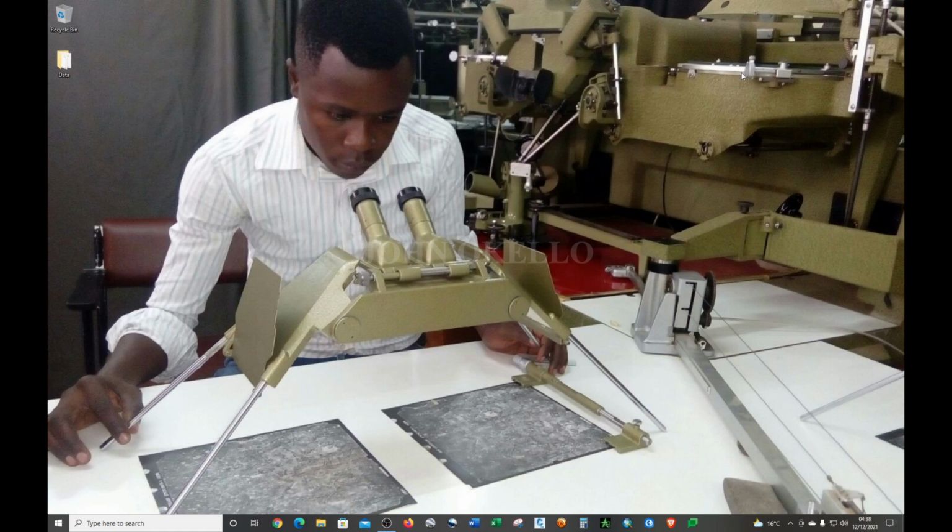By definition, digitizing is the process of converting geographic data, either from a hard copy or a scanned image, into vector data by tracing the features. During the digitizing process, features from the traced map or image are captured as coordinates in either point, line, or polygon format. And these points, lines, and polygons are what we call in GIS feature classes. By definition, a feature class is a collection of geographic features that share the same geometry type and the same attribute fields for a common area.